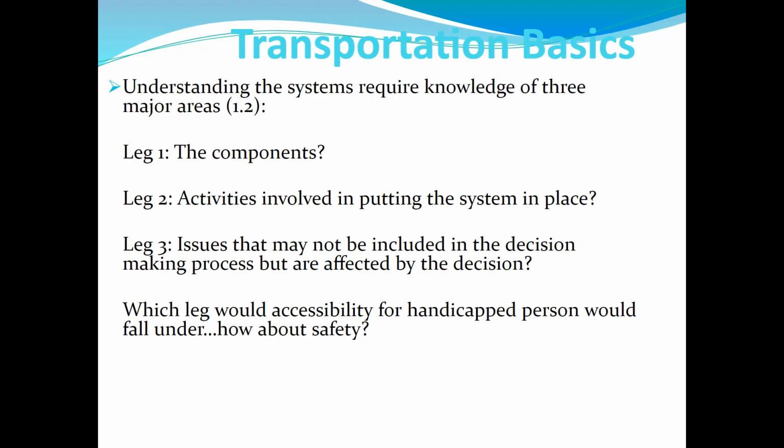For example, we accounted for the force that you'll require to stay on a curved path. We always made sure that the radius of that curve was appropriate, so that you could travel at the design speed on that curve. So that was always a leg two issue, and we call that the nominal safety terms.